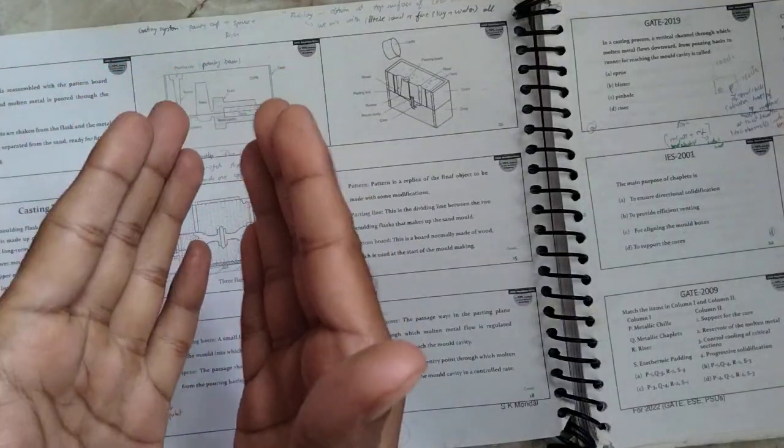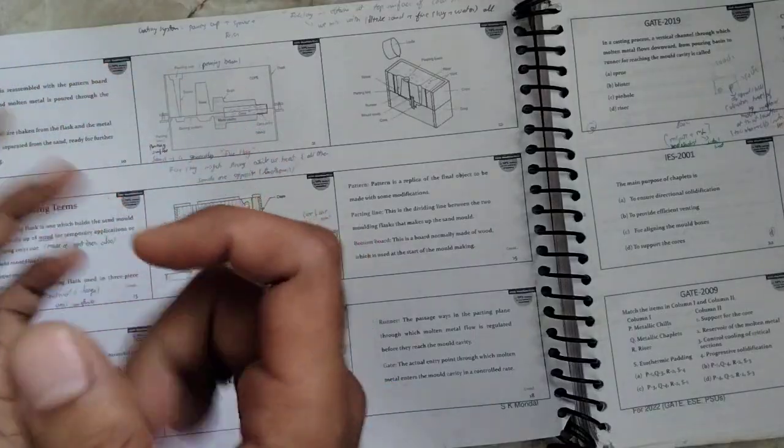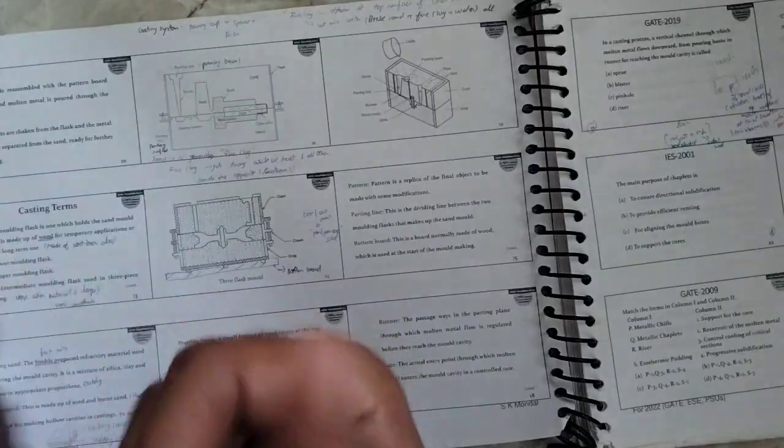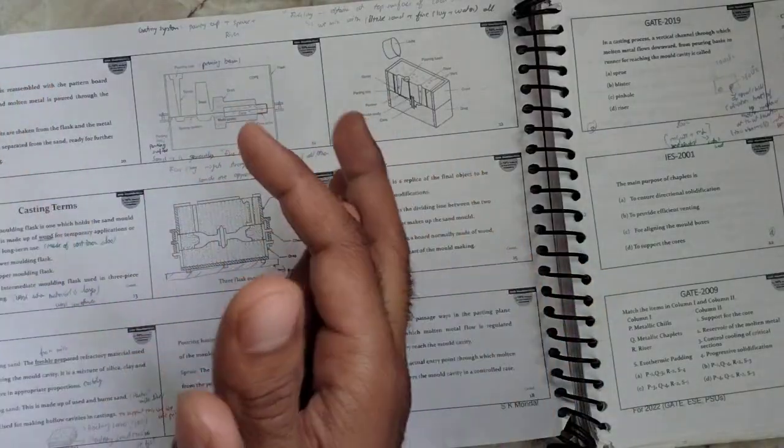Later I explained the pouring basin and how the runner will be, as well as the pouring cup, the sprue, the in-gate area, and how the sprue area will be on the runner, as well as the in-gate, the entering part of everything. And the riser. I also told you about the yield, the percentage of yield: volume of the cast divided by volume of the cast plus the volume of the entire remaining gating system.